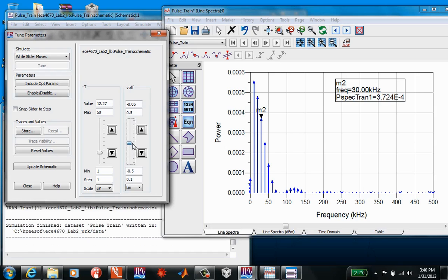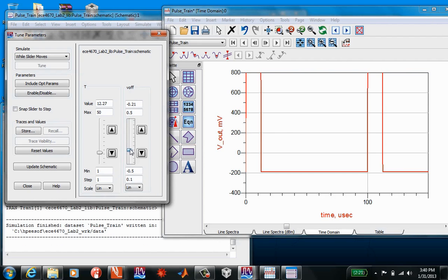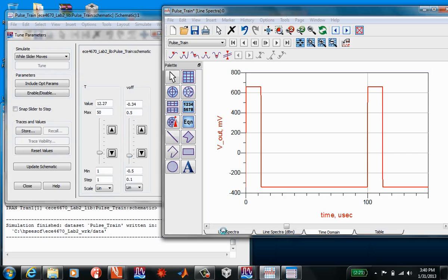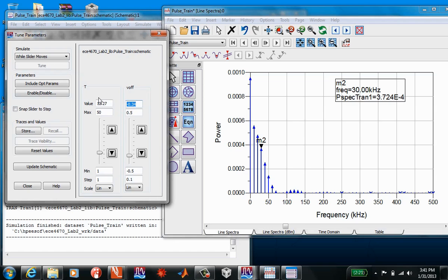And this is where the video is probably going to mess up on me, but it's going down, nulling it, and I go more negative, and it comes right back up again. Does that make sense? Because I'm now biasing the waveform too far negative, so now all this area is bigger than the positive area. Okay, I'm going to take that and just set that back to 0 again.